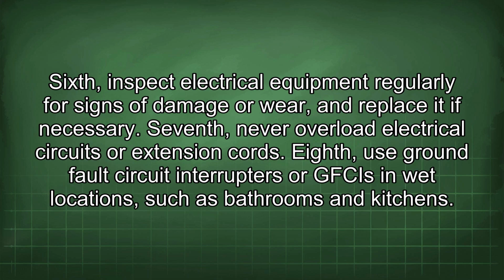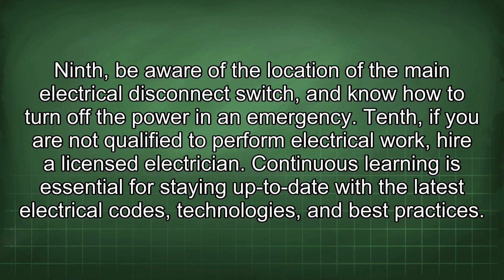Eighth, use ground fault circuit interrupters, or GFCIs, in wet locations, such as bathrooms and kitchens. Ninth, be aware of the location of the main electrical disconnect switch, and know how to turn off the power in an emergency.